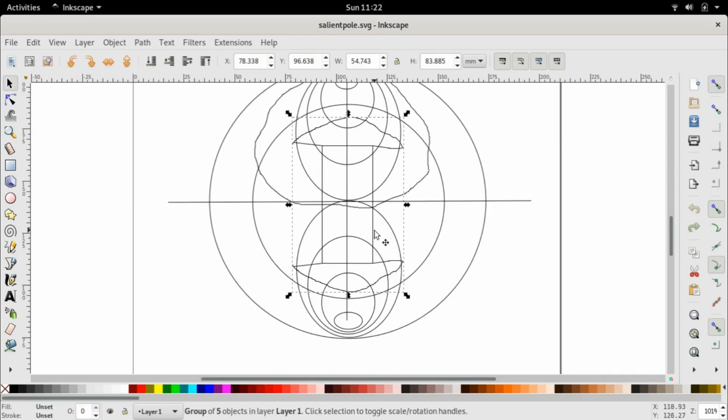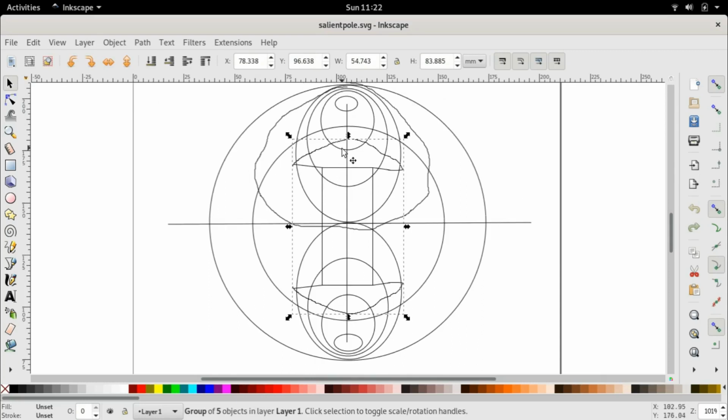And we can see this. For example, if we rotate this, we will see that in this direction, the flux is the weakest because the air gap is the smallest only in the area covered by the salient pole, and in all other positions, in all other places, the air gap is the largest.